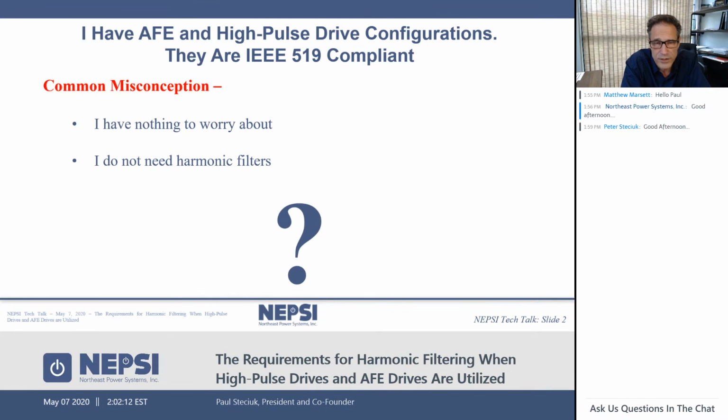So I often get this question when I get phone calls about high pulse drives and AFE type drives. Oftentimes the customers will say, hey, they're IEEE 519 compliant, I have nothing to worry about. They want to install power factor correction and they're going to install standard capacitor banks. And oftentimes they would say, hey, what's the big deal? I have AFE drives. They're compliant and I have nothing to worry about. So the answer to this question in short is yes, there are some things to worry about. And today we're going to discuss some basics and then get into why you need to worry about it and when you need to worry about it.